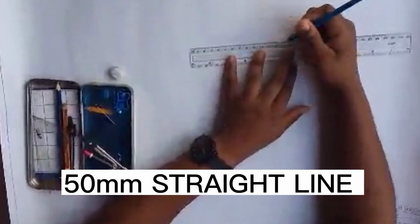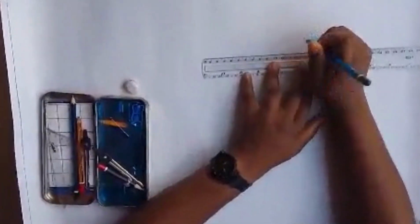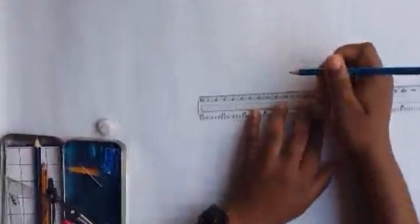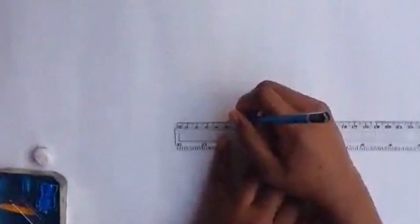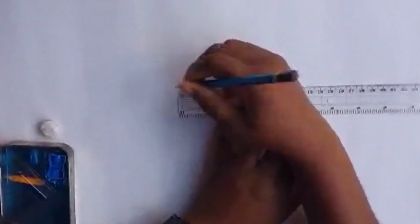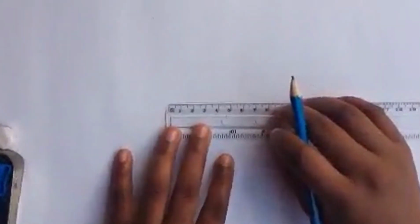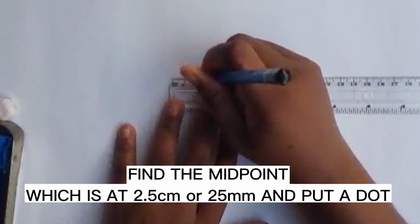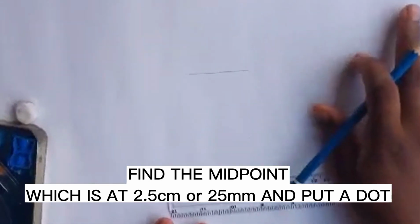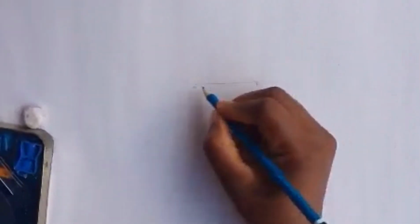So today we're going to be working with a 50 mm straight line, but since I'm going to be using a centimeter ruler, we're going to work with 5 centimeters. So you draw a straight line. You can choose any length of your choice. My line is 5 centimeters. Okay, so I'll find the midpoint, and that's 2.5 centimeters. I put a dot. So let's just label here A and here B.